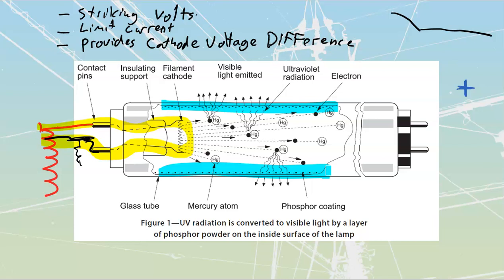Where we do use them is sometimes in manufacturing, because they allow us to highlight imperfections. If you've got a piece that has been milled and has cracks, those cracks are going to pick up contaminants, and those contaminants are going to glow. So we will use them for that. You'll also see some of these black lights being used to pick up invisible inking marks. A lot of our components have invisible inks on them that are used during manufacturing to identify stuff. But when the consumer gets it, they want a nice plain looking component, so they don't want to see any of the inking. But when it's going through the factory floor, we need to read that. So we'll use them for that.